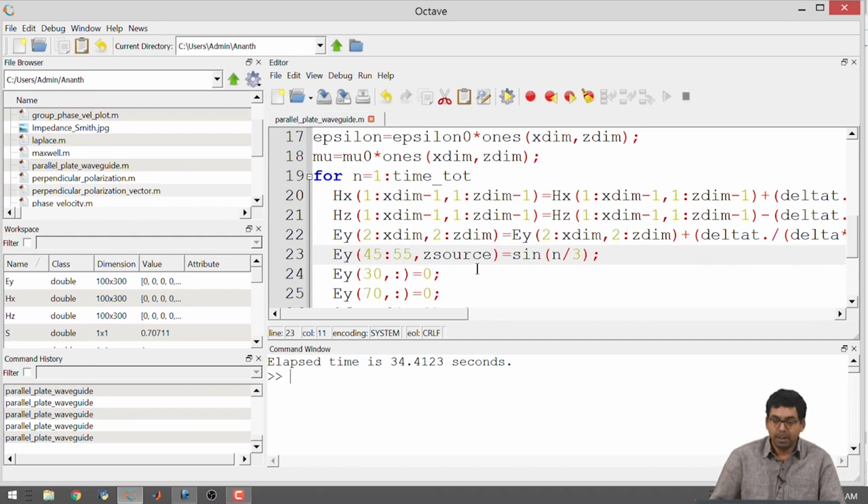So, now this part is now very clear, alright. Now, we will just make a couple more things, right. I had a waveguide going from left to right, okay. Now, what I am going to do is I am going to introduce a 90-degree bend, okay, but I am going to make this an abrupt 90-degree bend. So, I am going to launch it from one side, right, and I am going to abruptly try to see what would happen if I kept a perfect conductor 90 degrees, alright. So, that I would really know whether it is doing some waveguiding or not.